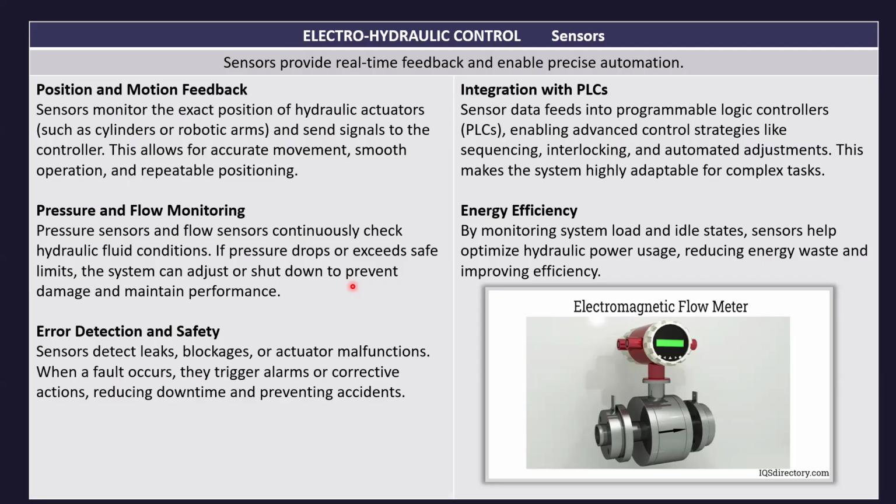So in the wet system, the pipes are filled with water and the water is under pressure. If one of the sprinklers is broken because of fire, or somebody breaks it with a ladder, then the pressure drops because there is water squirting out of that sprinkler.